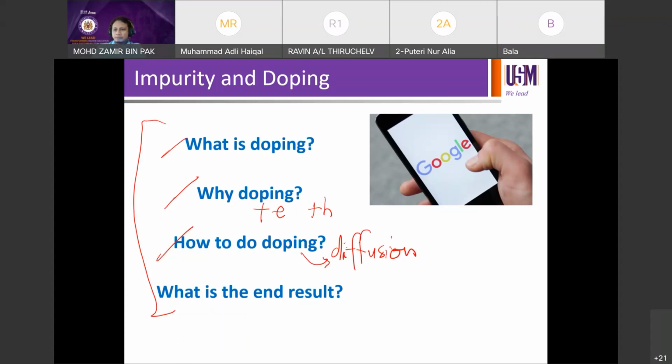How do you do doping? Lattice diffusion, inner lattice diffusion. Yes, you're incorporating impurities into the lattice. Introducing non-equilibrium charges. Yes. Remember last time I talked to you about we're going to be in equilibrium condition, and then we can introduce external factors such as impurities, light, electric field in order to alter the equilibrium condition, to introduce new carriers, excess carriers.